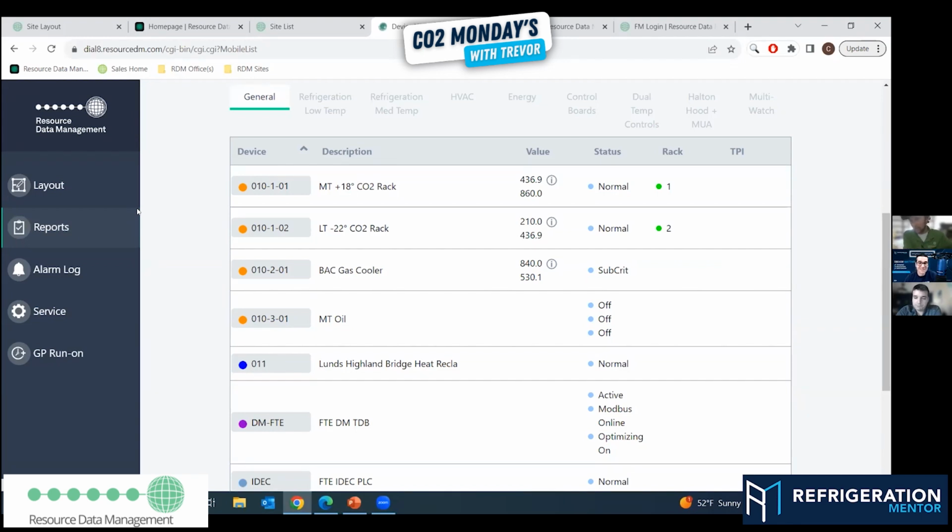And then all of a sudden in the back of the store, you don't have all that humidity and you've got the same set points. And techs always wonder why, well, my case is going through defrost, but it's still freezing up. Well, yeah, you have to look at these certain things. And there are settings in the controller that can cause that 100%. In a minute, we'll go over that, and we can walk you through some of the settings to look at.